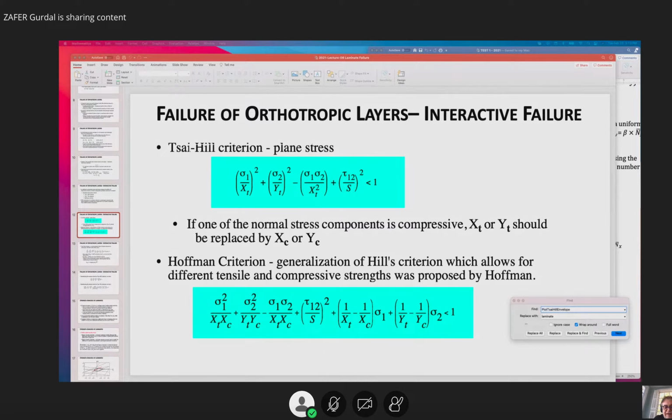This becomes a very hard, very difficult discrete optimization problem when you start saying that the relative location of the layers makes a difference. In which case, there are very few ways that you can solve this optimally. And trying the enumeration will be a horrific job, trying to find the relative location of each of those plies.